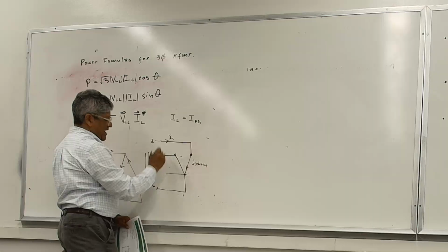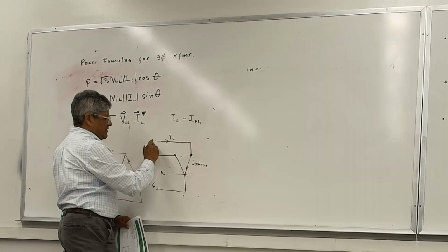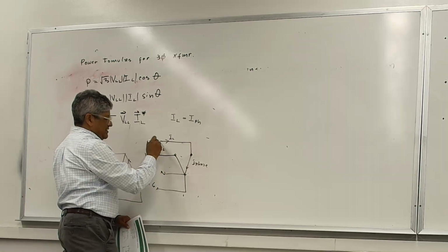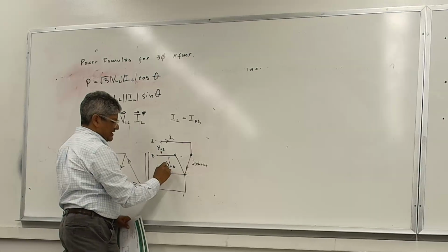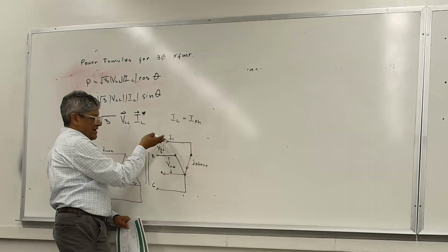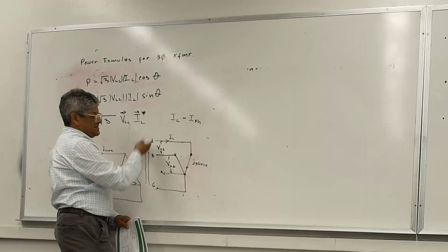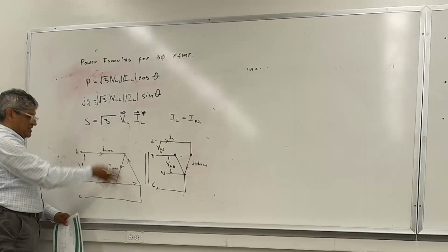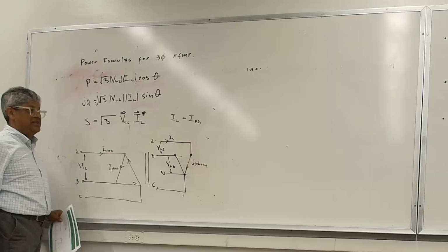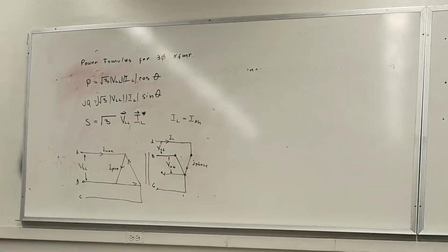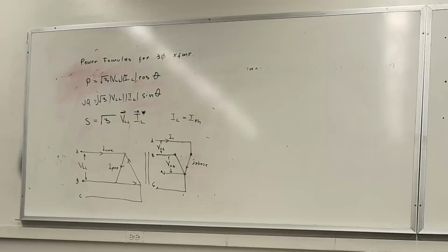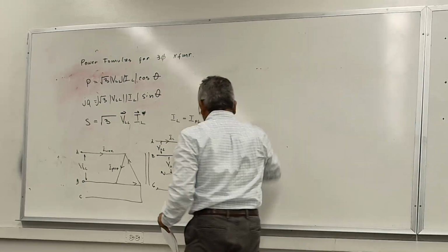And then in this case, we have a neutral point right here. So we have V line-to-line, and then V line-to-neutral. And I think we talked about this already, where you have 3 currents and 6 voltages. In this case, you have 6 currents and 3 voltages that you're dealing with, right? So same thing as when we were talking about three phases. But now we're connecting, obviously, transformers. Okay.